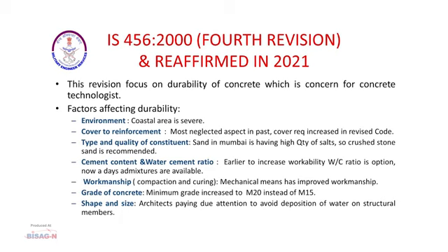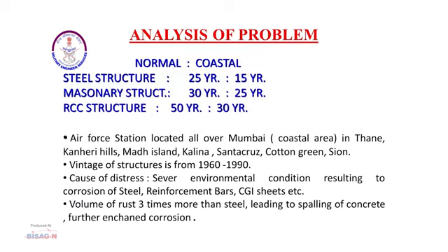It is the duty of the structural designers and architects to pay attention to the design of the structure so that water deposition doesn't occur there. As we are all aware, in the coastal environment the life of the structure reduces significantly, to the tune of 60%. For steel structures, it reduces from 25 years to 15 years, masonry structure 30 to 25 and RCC structure 50 to 30 years.